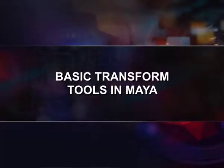Let us discuss the basic transform tools in Maya. Transform of an object means 3 functions: position, rotation and scale. Each function has 3 components for x, y and z. So, transform contains 9 variables in total, 3 defining each function. In transform, you need to move, rotate and scale the objects to place them in the position you want. You can move, scale and rotate the primitive objects into their final position either by direct manipulation or by entering numeric values through an editor.